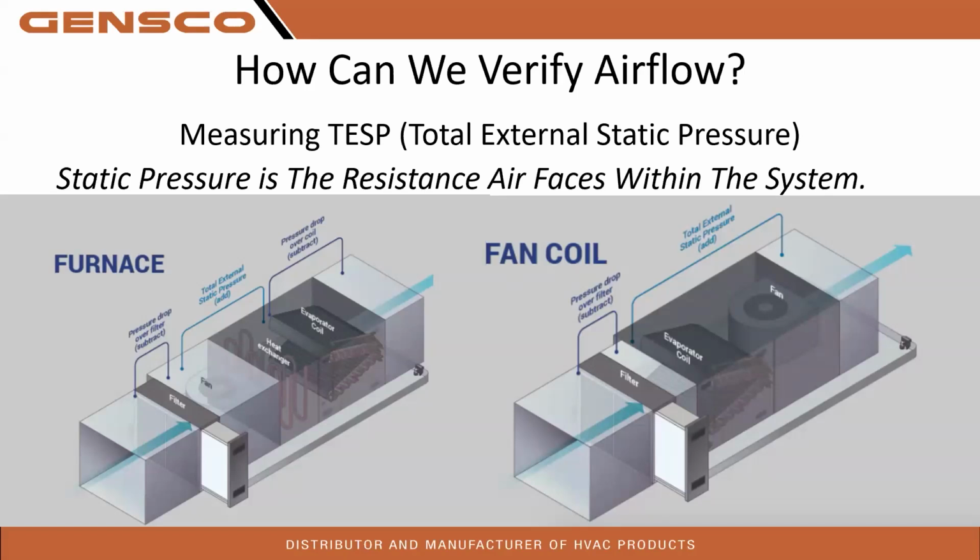I know a lot of you are using a TrueFlow plate. Awesome. I love it. That is your second way of measuring airflow. Your first way of measuring airflow is what the manufacturer wants to see. You verify it with a TrueFlow plate. You do not use that as your primary, because there are a lot of parameters that you may not see.